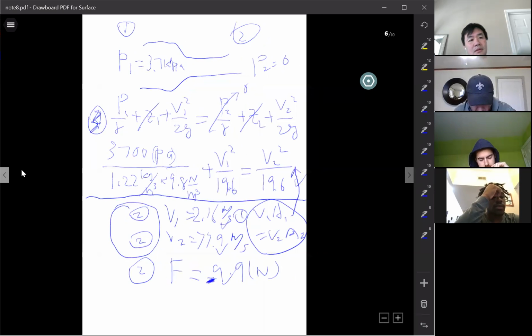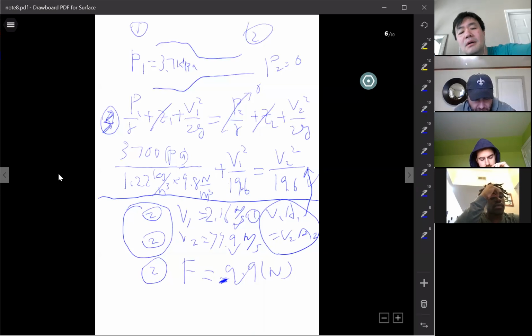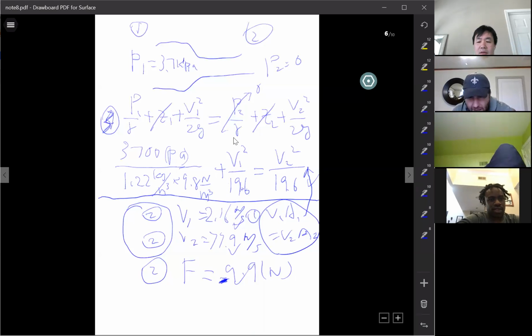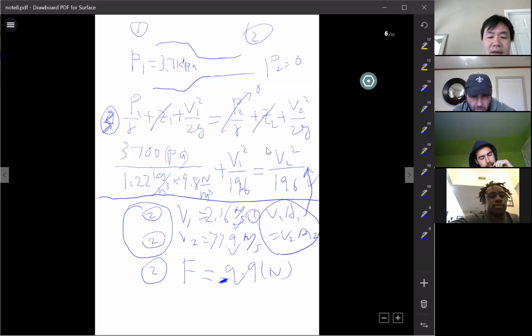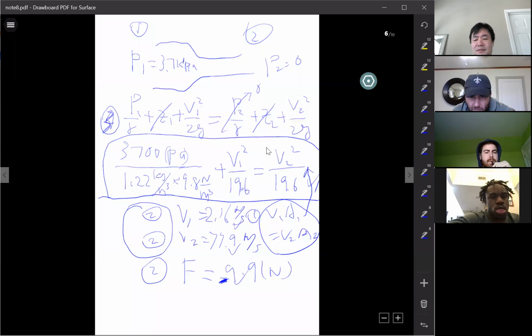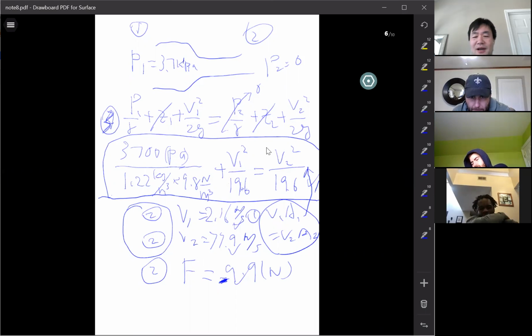So with the conservation of mass formula, you solved and plugged it back into the momentum formula, which you set equal to 0? Otherwise, you would have had a velocity variable that you didn't know and a force that you didn't know. Yeah, listen. Here, when you look at this equation, don't worry about the momentum. Now I'm in the Bernoulli equation to calculate V1 and V2, right? When you look at this, do you have 2 unknowns there? You have 2 unknowns, V1 and V2. So one equation for 2 unknowns doesn't work, right?